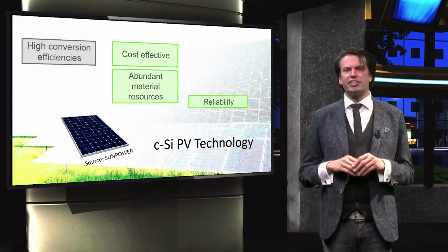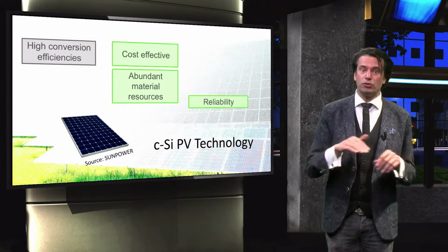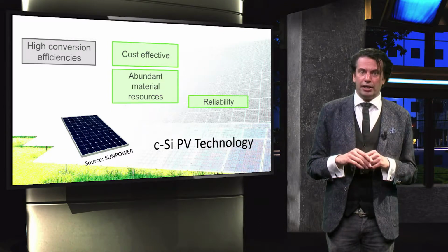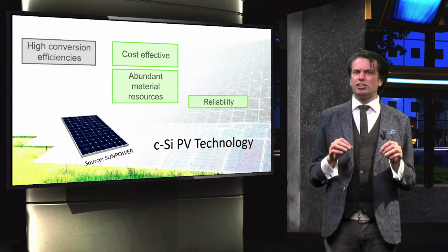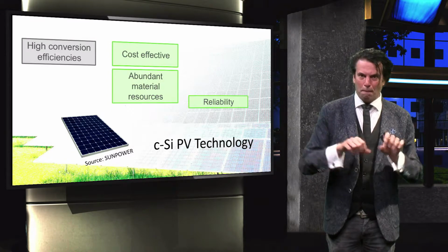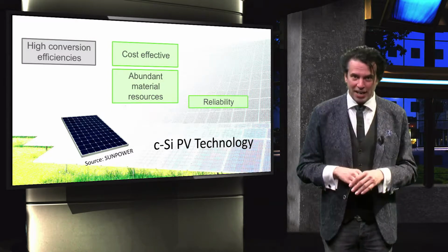A disadvantage of crystalline silicon modules can be that they lack the flexibility to adapt to the building geometry. They have lower performance under shading, and the modules are sensitive to mechanical stress. Bending or walking over modules might result in breaking of the wafers.